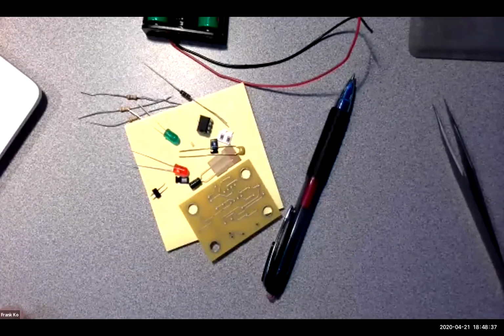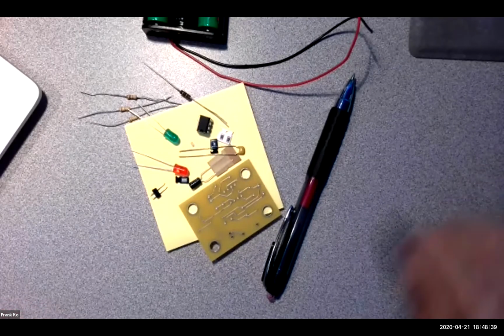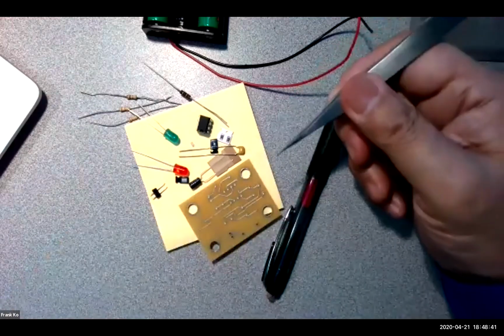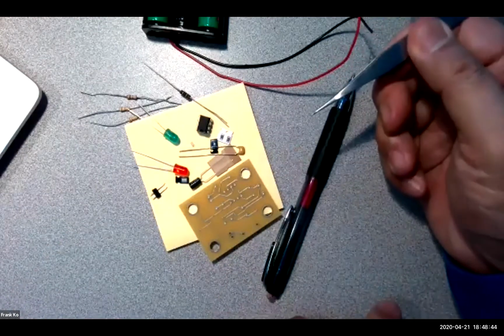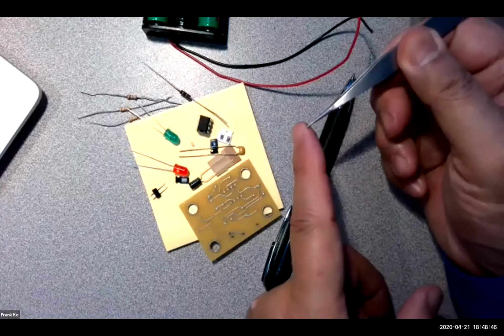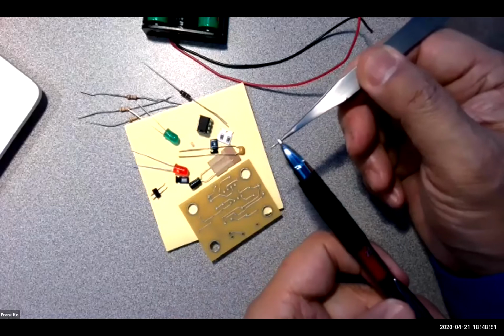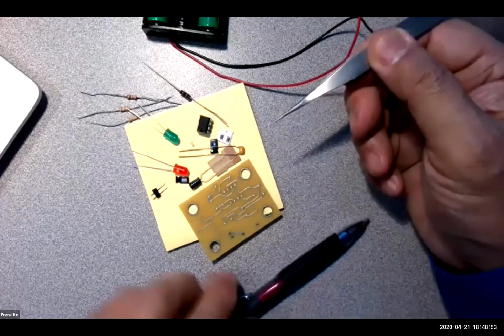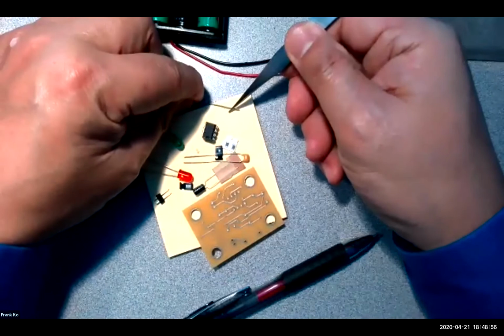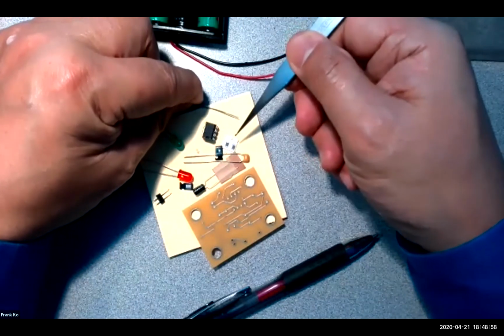In proper technique, you're not supposed to use the tip of the soldering iron, but in this case, would you, or would you still do the same technique? To answer the first part of your question, yes, we usually, so pretend that this pair of tweezers is the point of an iron. We usually use the shaft, the shank part of the iron right here to heat up a wire while it's sitting on the board through a trace.